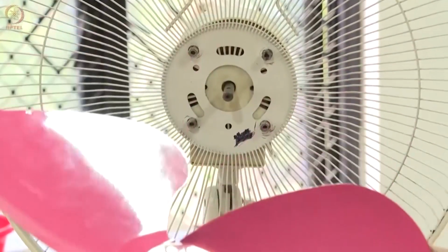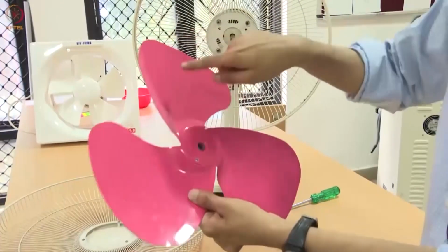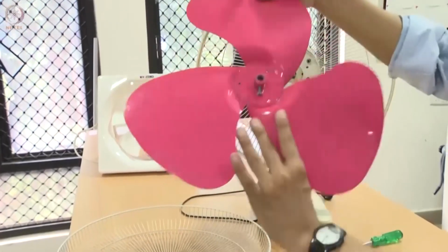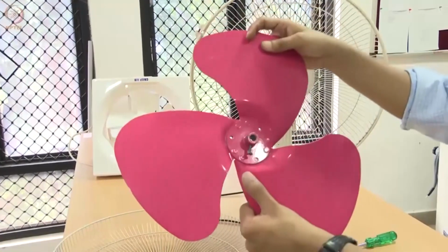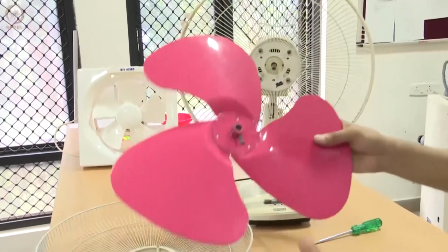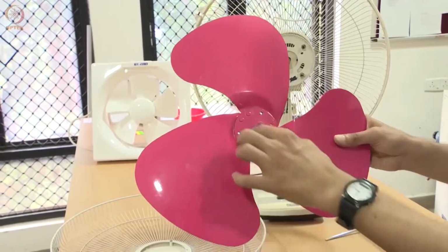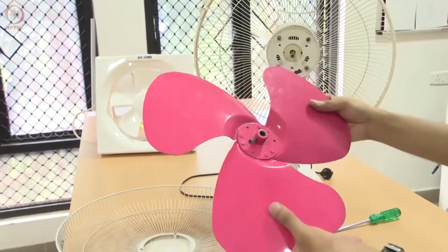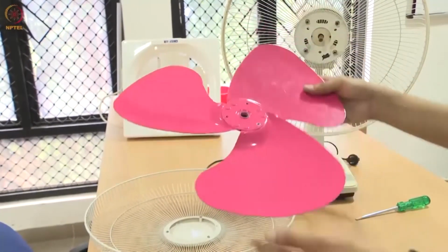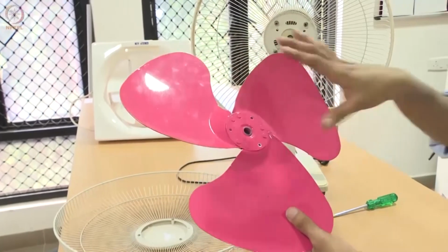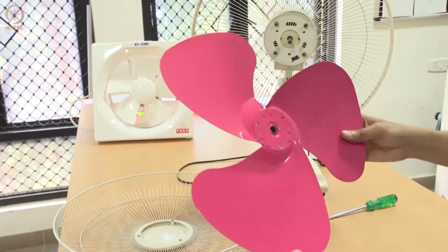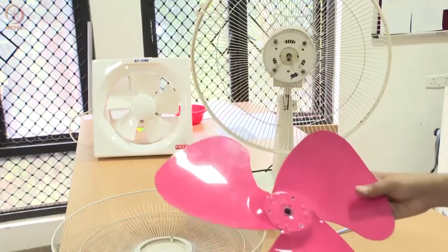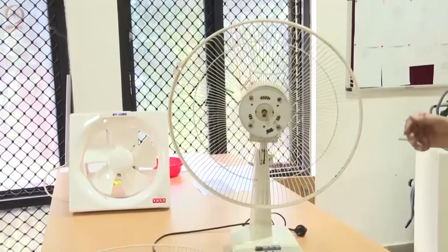Talking about the fan blade itself, it's a 5-part assembly. You have 3 blades, and then you have a disc here, and at the back another disc with a boss. Since you never intend to dismantle this in practice, all the parts are riveted together. At the manufacturing site, they make sure the tolerances and the dies used to make this fan blade are very precise. So as soon as the fan blade is manufactured, it has reasonable dynamic balancing that is controlled through the process. That is something you should keep in mind. Now let us proceed dismantling the fan further.